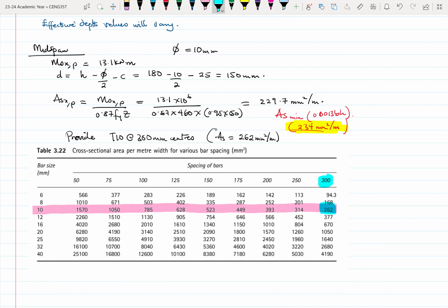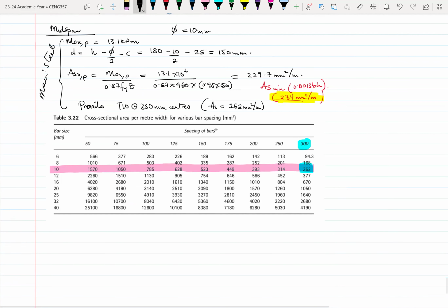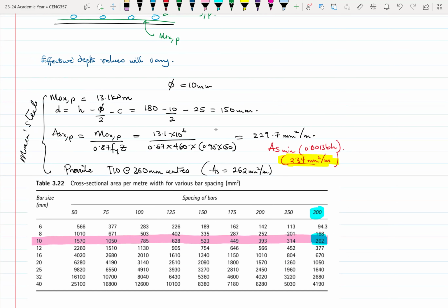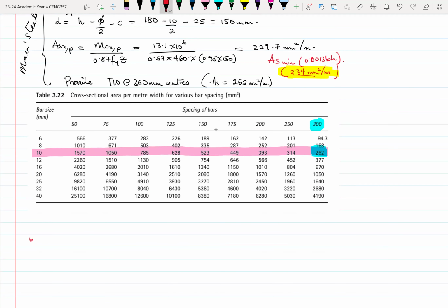And this is basically, we call the bar in the shorter span the main bar or the main. So some will say this is the main steel. So let me put it here rather, so that it's actually here. Okay. So we are still on the mid span. So we have the mid span A where we are looking at the main steel. Then the mid span B will be what we call the secondary.